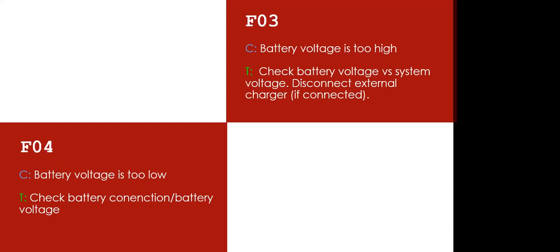In the Gennex inverter, we have a cutoff voltage that we program for our system, which makes you maintain your battery very well so that you don't overuse the battery. So we have a cutoff voltage for all our inverters. Once the cutoff voltage is reached, the inverter will show F04. And when it reaches the lowest voltage set for the inverter, it will go off permanently until you charge it to the point where the inverter senses it as an appropriate voltage to operate on.